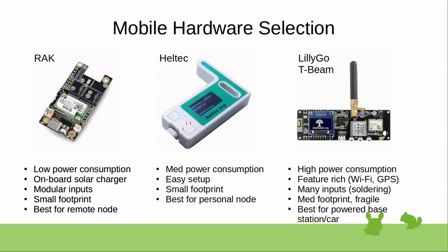This guy runs off of one of those boards. I believe this is a 3000 milliamp hour battery, and this guy lasts with GPS and other sensors and screens on it the better part of a week. This guy in here has a little solar power on the front of it. And these ones I specifically put in two 3000 milliamp hour 18650s, and that can run for the better part of 2 weeks, up to 3, depending on what sensors are on this specific node, how often it's chirping out, that sort of stuff. And with the solar panels, all of our routers are built that way up on mountaintops, and we only have to go up to them for maintenance.